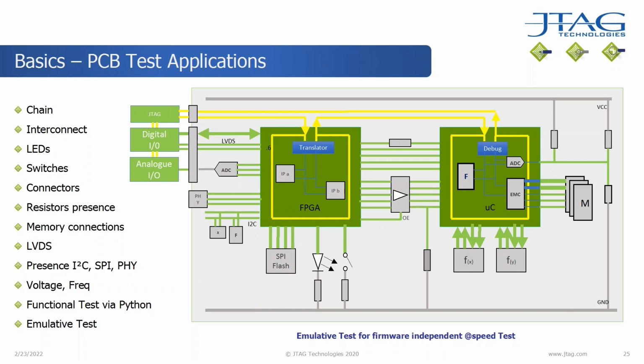In the olden days, it would be an ARM7 or an ARM9, but now we're looking at Cortex cores, Cortex-A, Cortex-M, that type of thing. And via the JTAG interface, we can set the devices up into their debug mode, and from the core, we can set up memory writes and memory reads in order to set up the embedded controllers and elements within the device.